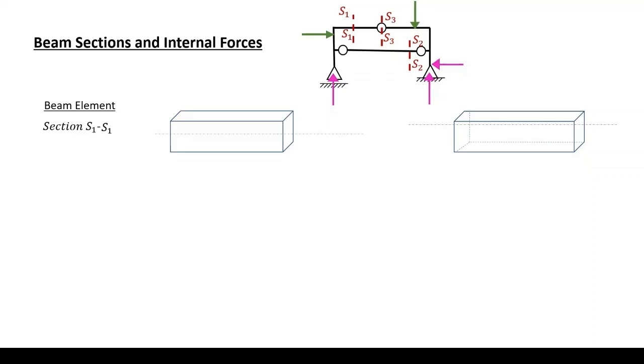The internal forces that appear are N, normal to the cross section here, and in the direction of the center line of the beam. A force N equal in magnitude and opposite in direction is on the right section to maintain equilibrium in this direction.